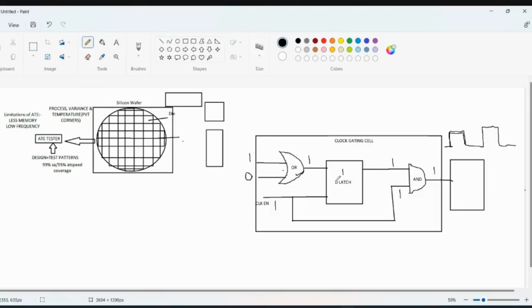So this is a D latch. It's level sensitive. Level sensitive means when it is high, it is high. When it is low, it is low. It's not like a flip flop, which maintains one full clock pulse. A flip flop will maintain one complete clock pulse. For a D latch, it will latch out with a half cycle of that particular clock. The half cycle duty cycle of a flip flop is equal to the full cycle of a D latch. So it's just 0.5 nanoseconds.